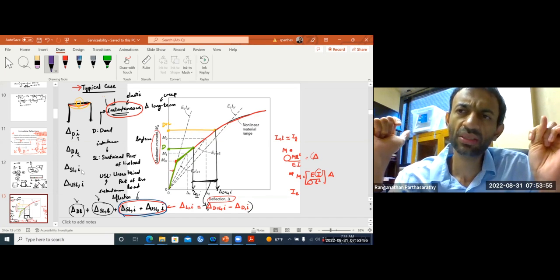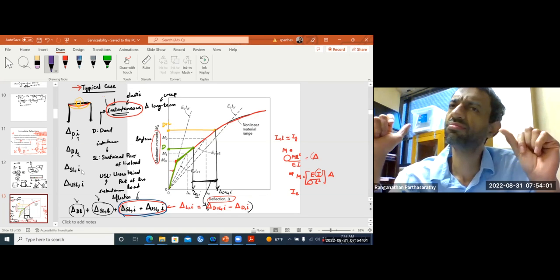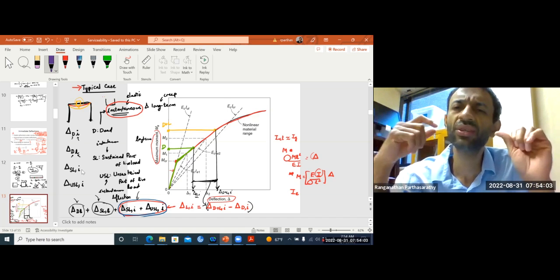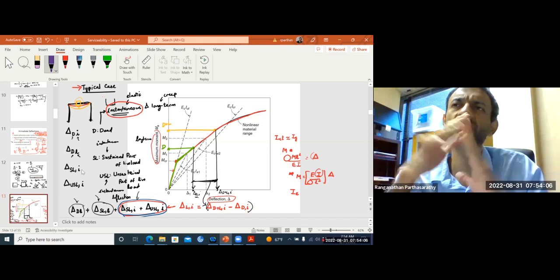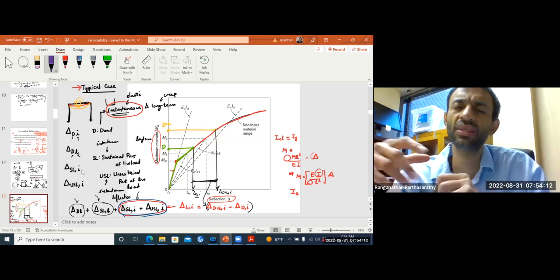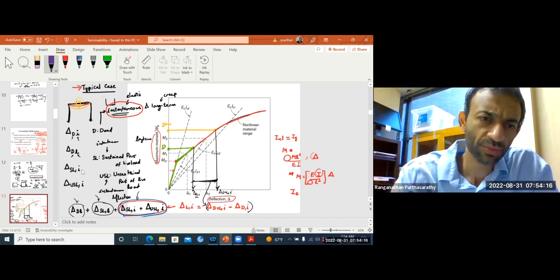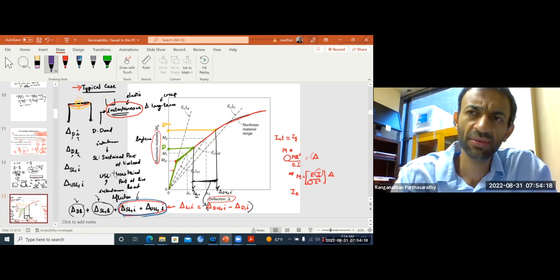Now sustained is something like you bring in some big piece of machinery, it's going to sit for good, or for a long time. So that will be considered as a sustained live load. Even though it is not a dead load, it's still going to be acting for a while. So for sustained live load, you will calculate instantaneous deflection as well as long-term deflection.